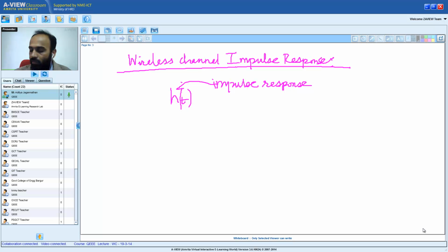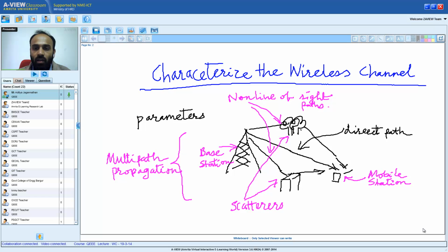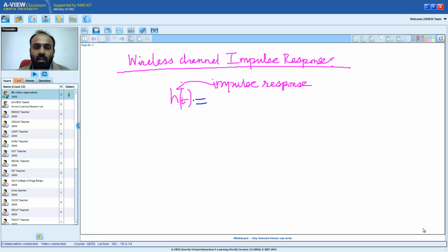Okay, that is fine. We said that the wireless channel is basically the sum of several impulses, because there are several multipath components. That is, there is a signal copy, a slightly delayed and attenuated version of the signal copy, another delayed and attenuated version. So there are several copies of the same signal, and each copy corresponds to an impulse.